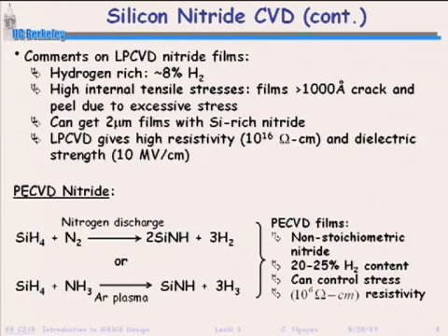So if you were designing a process that required a mechanical structure in a PECVD film and you wanted to play this trick to get that structure to be nice and straight, be prepared to spend a lot of time characterizing that process. And then once you've characterized it, if you leave it for a month and then come back, be prepared to characterize it again. Because PECVD, and this goes for all semiconductor equipment, unless it's used for one purpose over and over and over again, it's not going to be repeatable.